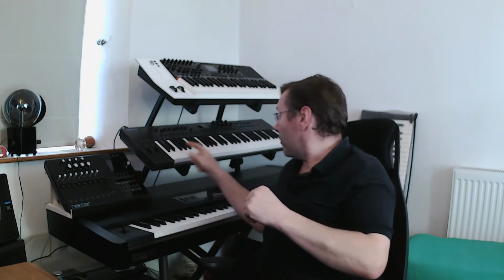In the MIDI world, when I hit that key, it'll actually send a little bit of data out to say note on. And then when I release it, it will send out another bit of data to say note off. But in the CV world, as I say, it will just go to a particular voltage and hold it there indefinitely until you let go of that key, and then it'll drop it down. But the note data is still sending whatever the last value I hit on the actual keyboard.